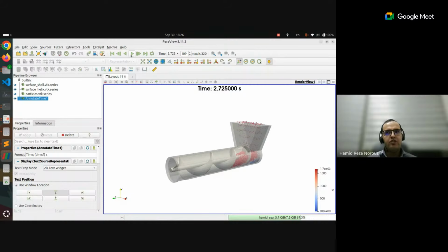It's really easy. Just calculate the mass of one particle, and then by dividing the actual flow rate of the solid by the mass of the particle, you will get the number of particles per second. Great, thank you very much. I mean that you just have this option to define the number of particles per second in the current version of PhasicFlow.